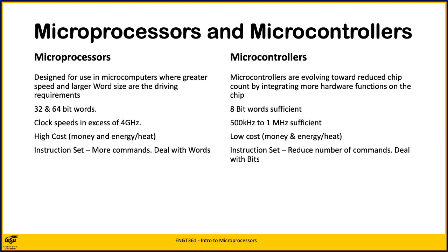The additional bit handling instructions were included because they were so useful in control system applications. For example, in a control system, each separate bit of a parallel output word might control a separate device, such as a motor or indicator light. The bit handling instruction allows the software to turn one device easily on or off without affecting the others.